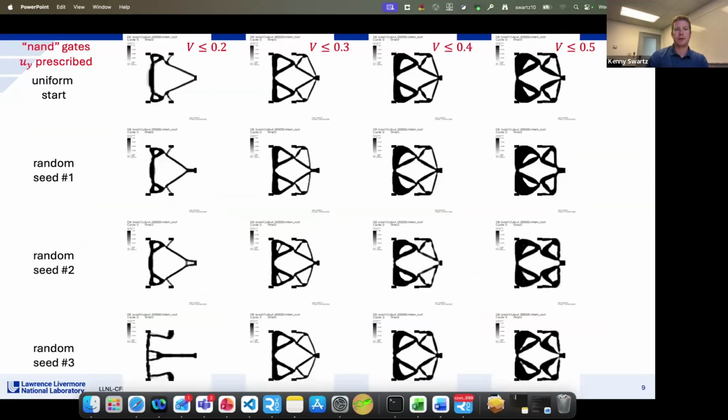And so one thing I want to point out as well is that I am using top-bottom symmetry here, so that the parameterization region is just really the top, and then that is mirrored over a symmetry plane. And in that case, I lied to you a little bit because I said there were 3 load cases. With symmetry, you only have to consider 2, since applying your displacement to the first input for a symmetric design will do the same thing as if you just applied it to the bottom. So there's really just the single input and the both input load cases.